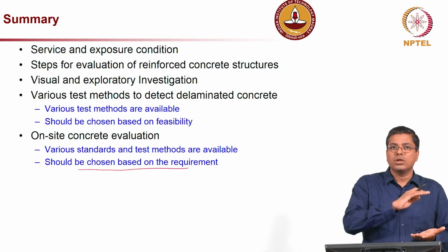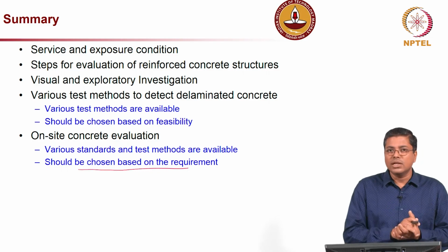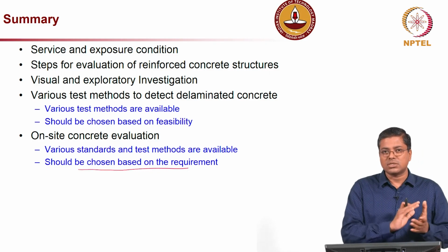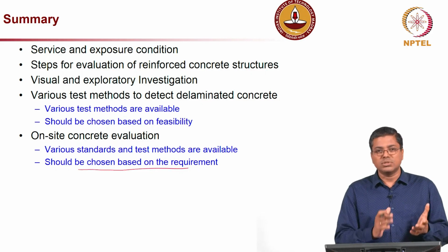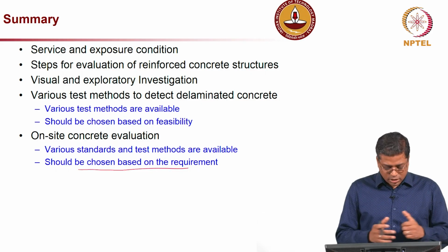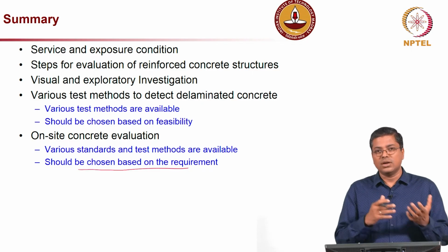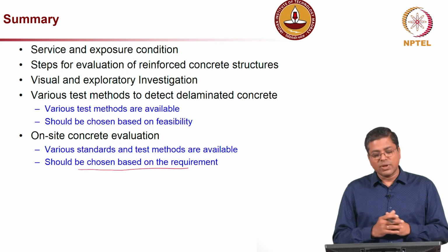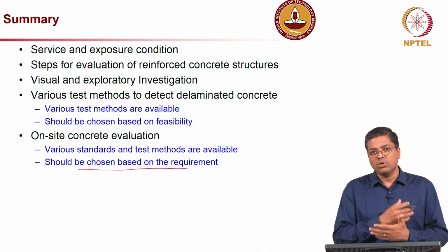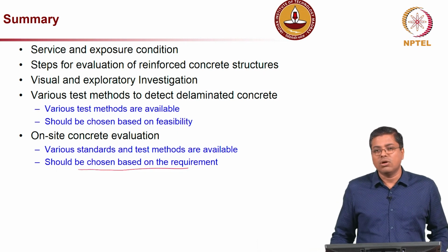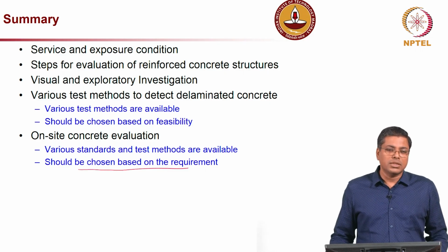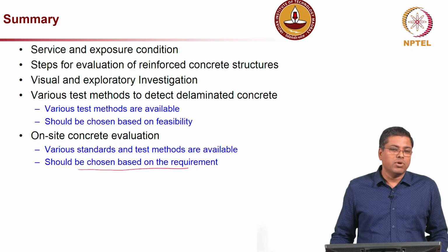So you have to look at the specific application, the size and shape of structural elements, and the exposure condition, whether it is wet or dry, and see which instrument will work, rather than going and doing all sorts of testing on the concrete.